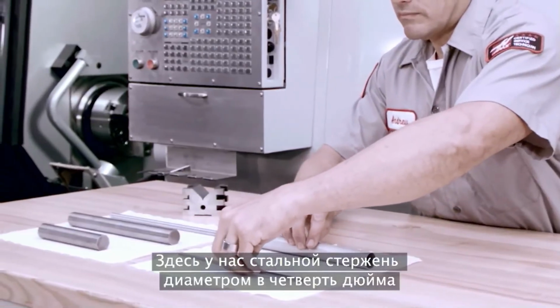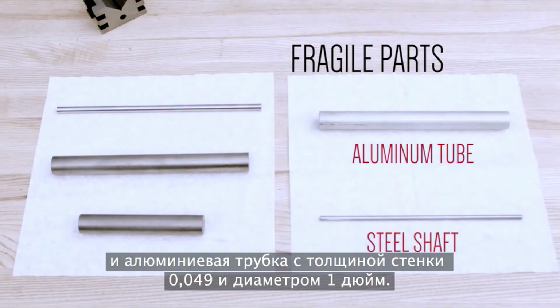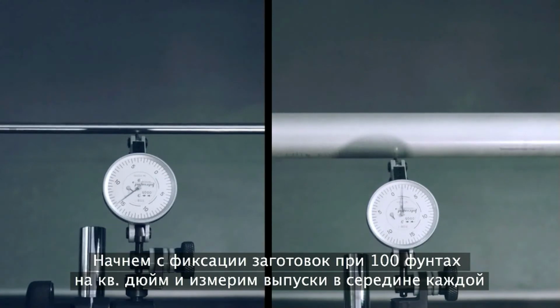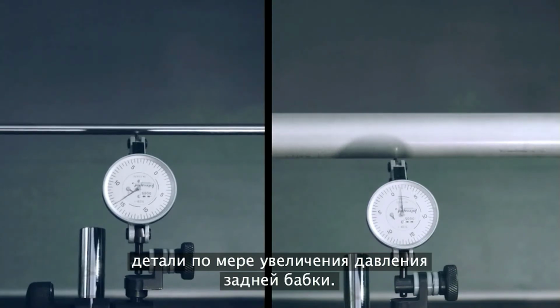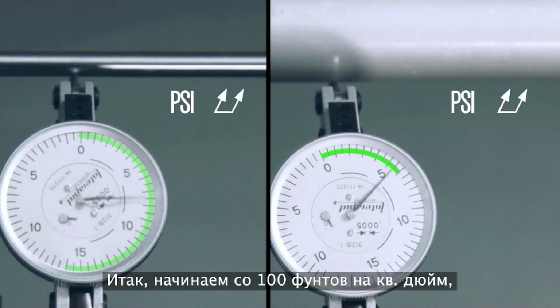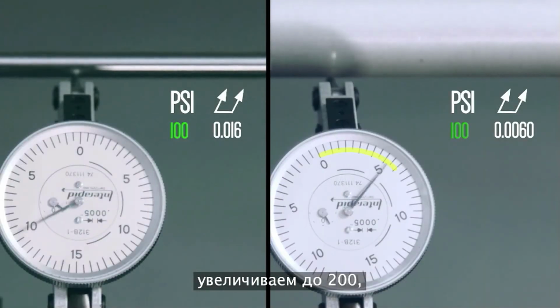Here we have a 1/4 inch diameter steel shaft and a 49 thou wall 1 inch diameter aluminum tube. How much pressure will it take to deform them? Starting with the parts held at 100 psi, we'll measure runout at the middle of each part as we make 100 psi tailstock pressure increases. Okay, starting at 100 psi, increasing to 200,